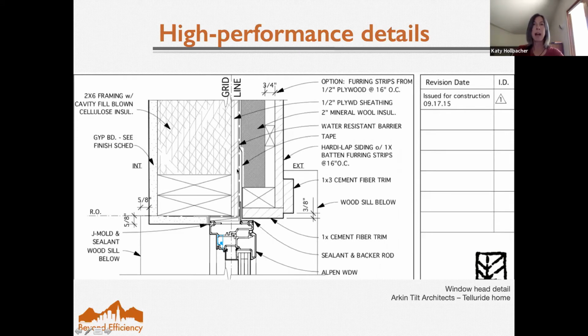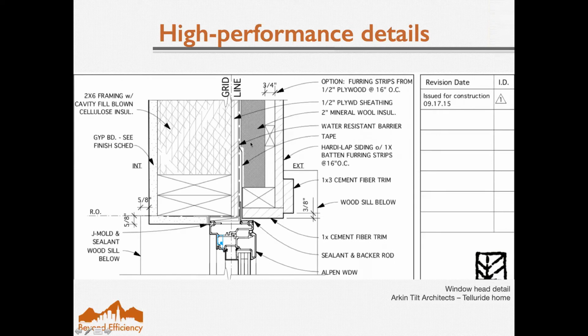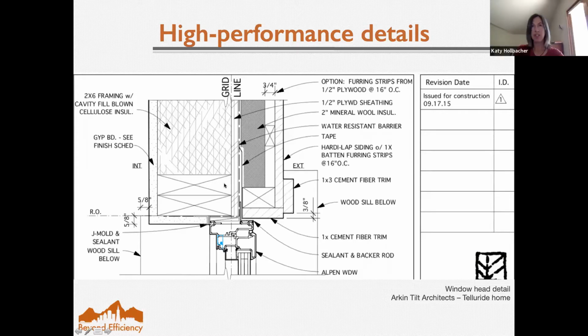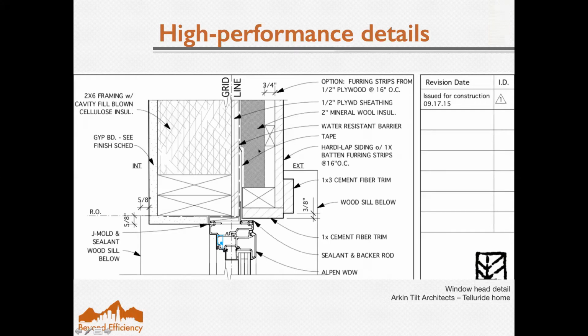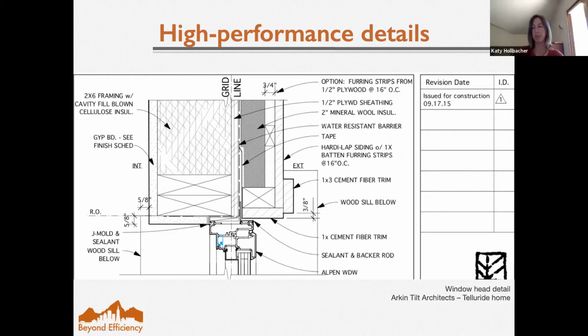So my best practice, my favorite approach is this sort of assembly, where you have cavity insulation, we have the sheathing, we have the WRB directly on top of the sheathing, which again is the weakest point. This also is functioning as the air barrier, so the insulation outboard of it is giving that weather resistant barrier that much more protection.